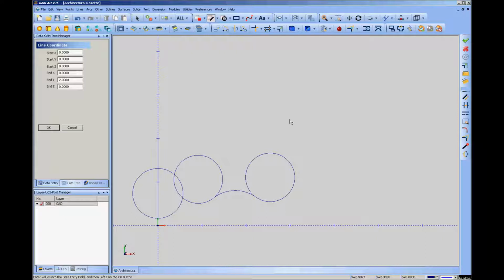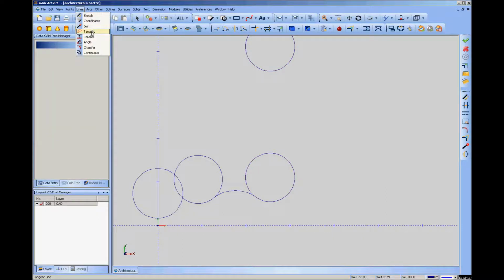Over here, I want to come directly vertical from this point, and the easiest way to do that is using the translate function. I will simply put a copy of this circle up higher. We'll translate it in y3. Okay, and now we can use lines tangent to draw that. Alright. Now I can get rid of that because it was just a construction point.